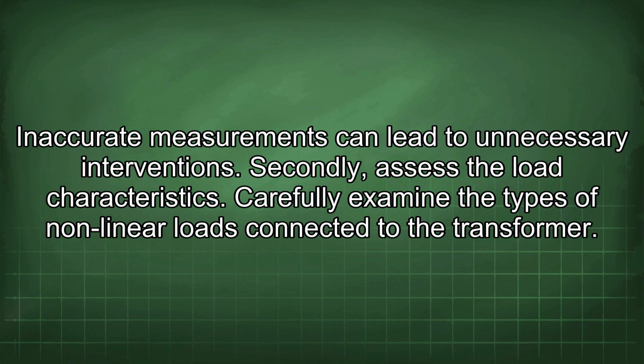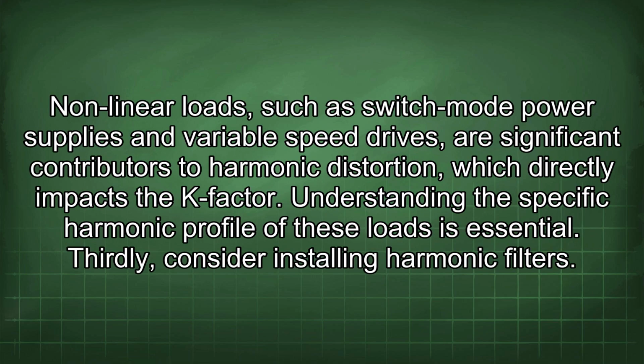Secondly, assess the load characteristics. Carefully examine the types of nonlinear loads connected to the transformer. Nonlinear loads, such as switch-mode power supplies and variable speed drives, are significant contributors to harmonic distortion, which directly impacts the K-factor. Understanding the specific harmonic profile of these loads is essential.